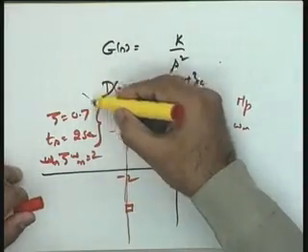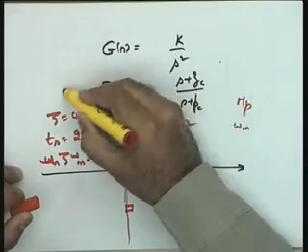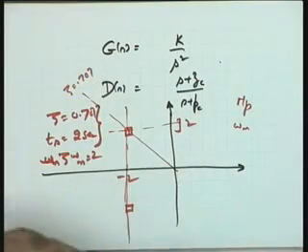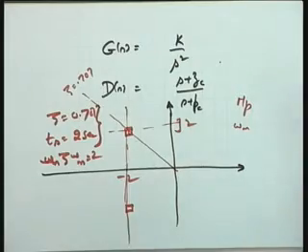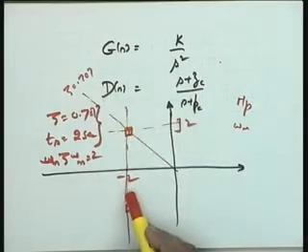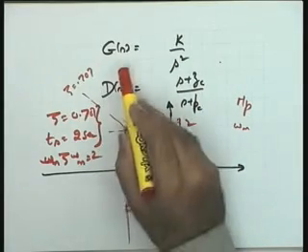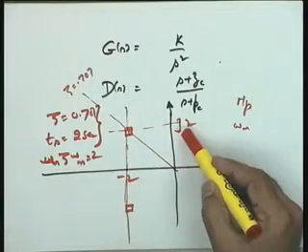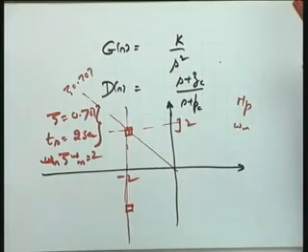You see that it's your zeta line. Zeta equal to 0.707, let me take it exactly as given in my notes. So this is the zeta line I have taken. Zeta omega n is equal to 2, so this is the vertical line. I get this as the intersection, which gives me minus 2 plus minus j2 as the desired locations of the closed loop poles. I hope this point is well taken.